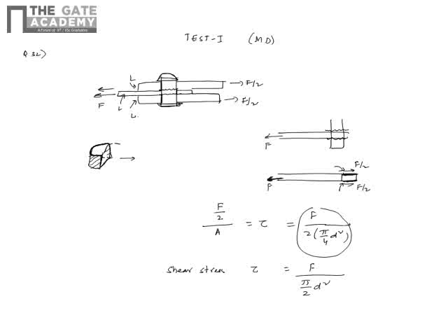So this is the total force divided by the projected area of this lateral part onto this. So it's basically your local pressure or local compressive stress. If you imagine that pressure is acting throughout this semi cylinder, then pressure into this projected area, which is your thickness into your diameter, is the crushing load.